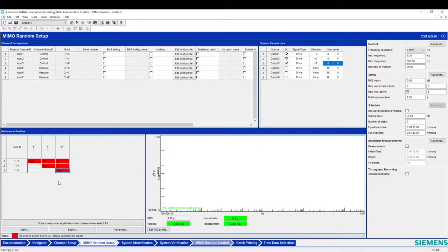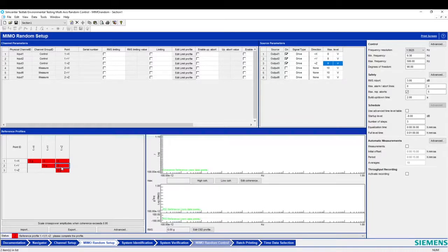And then, of course, we also have to define the correlation between each control channel by defining the phase and the coherences of the CSD, so the off-diagonal terms of our matrix. As you know, our control target is a symmetric matrix by definition, and therefore we can just define the upper triangular part to define the entire control matrix.